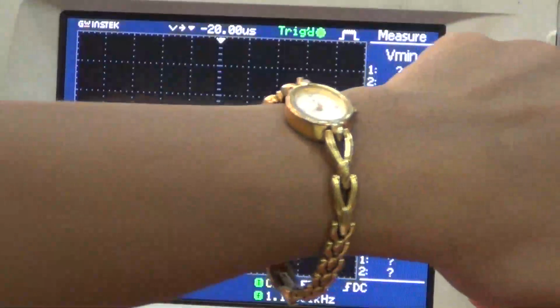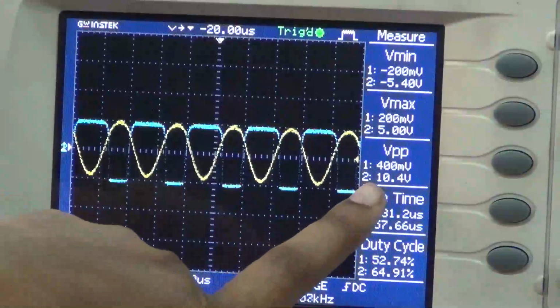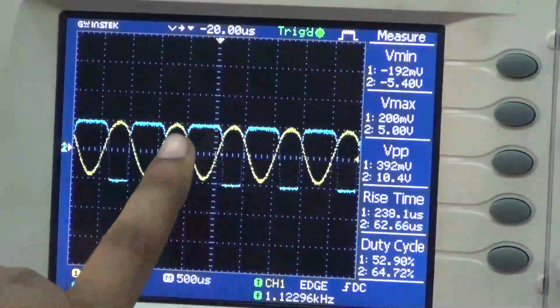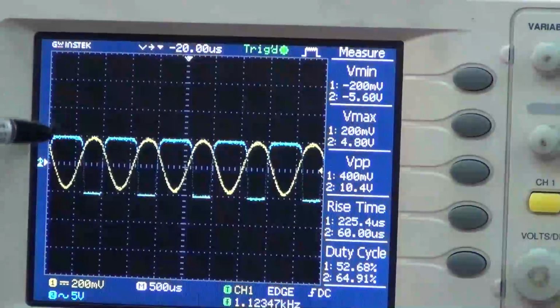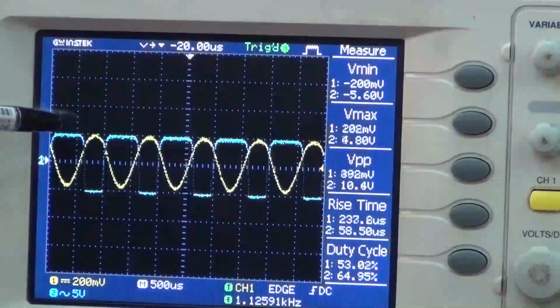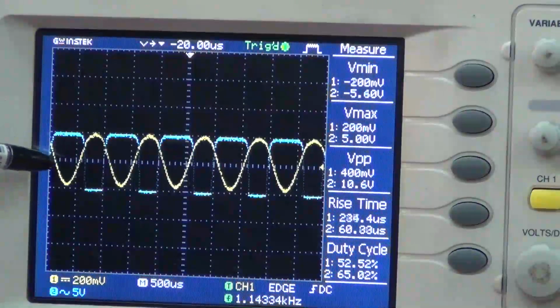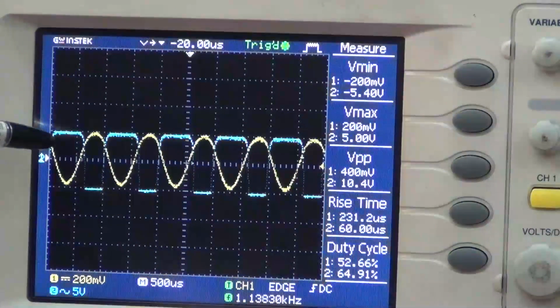So this indicates that the gain of the amplifier circuit is too large for the circuit to hold, and we have to decrease the input signal amplitude either using the function generator, or better to use a potential divider circuit as given in the handout. So that is all.